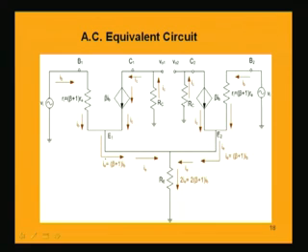Now, this current is flowing in this direction, which is IE, another IE is flowing in this direction, they will be combining and they will be together flowing through this resistance Re. So, the total current flowing through this resistance Re is 2 times small IE, IE due to this part, another IE due to this transistor. So, total will be 2 times IE flowing in this resistance Re. So, that is nothing but 2 times beta plus 1 into Ib.